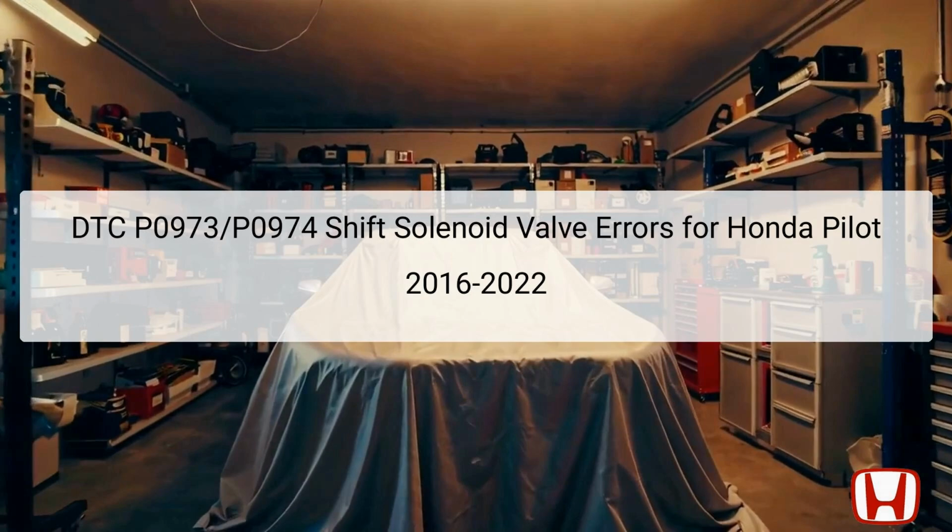In this presentation, we will explore the diagnostic trouble codes DTC P0973 and P0974, which relate to the shift solenoid valve in the Honda Pilot, manufactured between 2016 and 2022. DTC P0973 signifies a low input from the shift solenoid valve A, while DTC P0974 indicates a high input from the same component. The transmission of this vehicle relies heavily on the shift solenoid valve as it controls the flow of transmission fluid, facilitating gear shifts seamlessly.